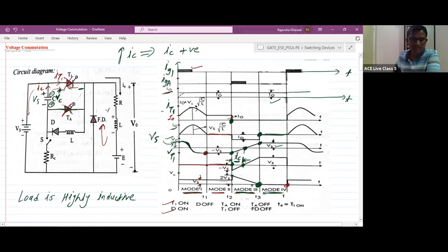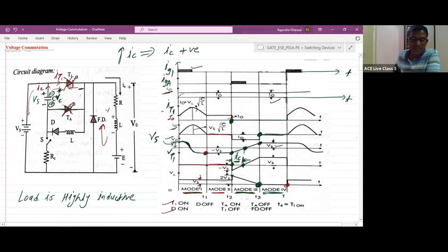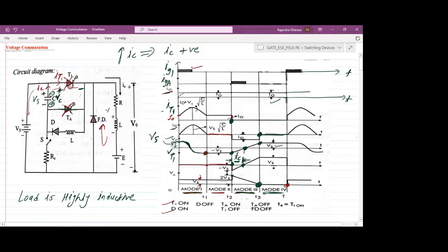Will you please repeat it? The main thyristor may face over voltages at the time that we discharge to the VS, no, sir? It may be damaged. Is there any chance of that? When thyristor T1 is damaged, can we say in practical application that the T1 is overrated because of the negative, discharging current through the T1, sir?